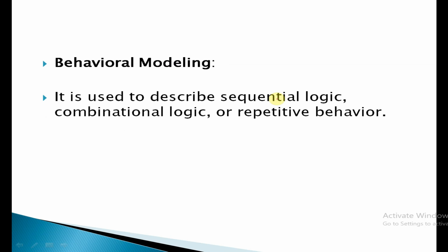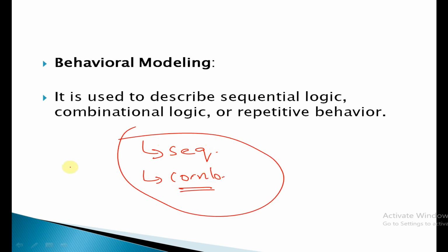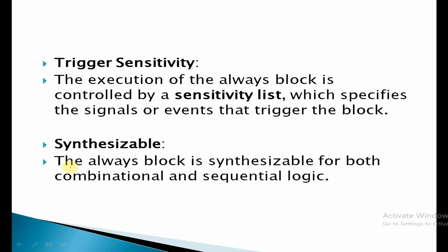It is also used to describe sequential logic, combinational logic, or repetitive logic. So we can use the always block for modeling sequential circuits as well as combinational circuits. The always block is also trigger sensitive, that is, its execution is controlled by a sensitivity list, which I discussed in the previous session.